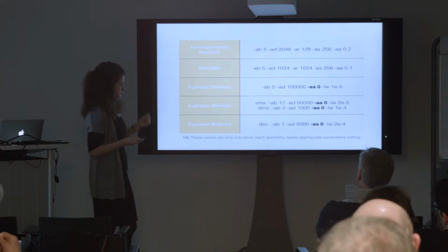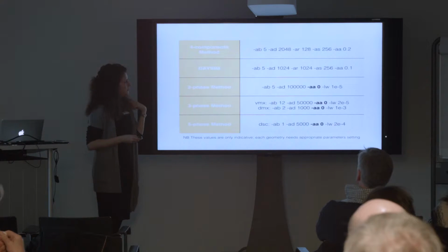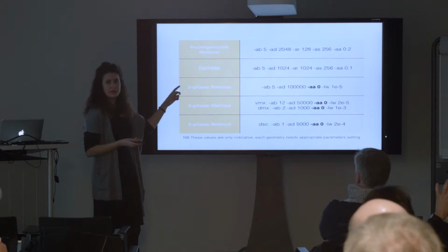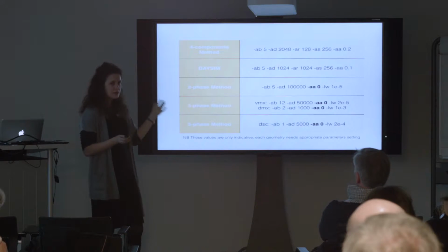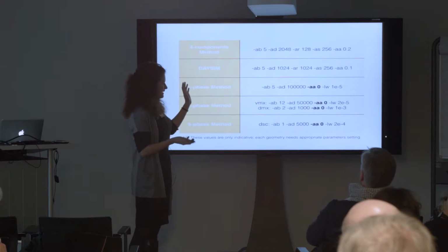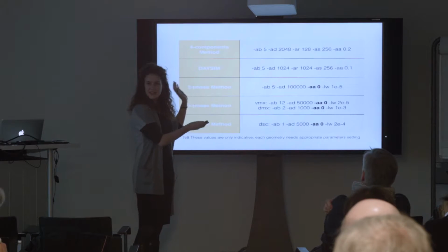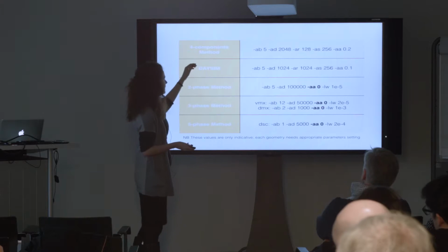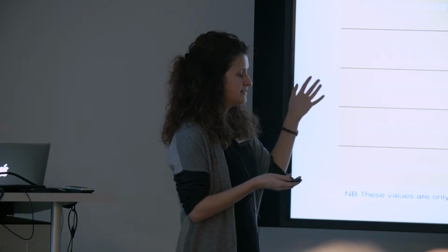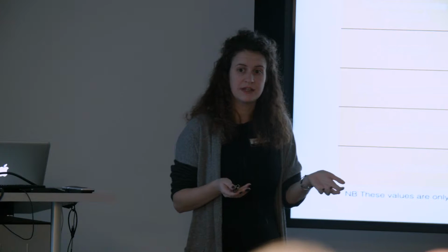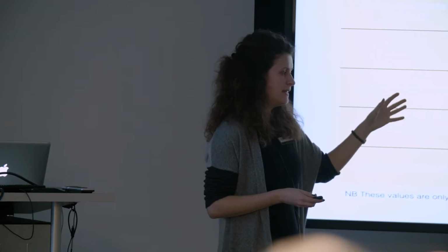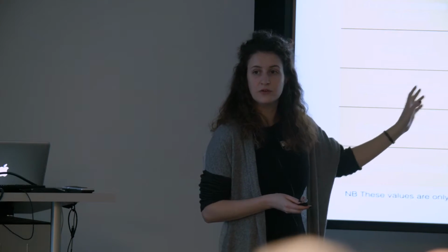And yeah, to recap a little bit about the methods, we can look at the radiance parameters that we use for each of them. They are always dependent on the geometry that you're simulating. So these are not strictly a recommendation to be taken as it is. But it's just to point out that the four-component method and DAYSIM were using rtrace, so you're using Radiance and setting it as you would for an rtrace calculation. And for the standard ones, from the two-phase method onwards, the settings need to be changed in a few bits.